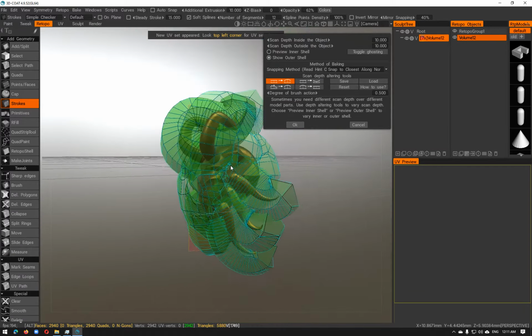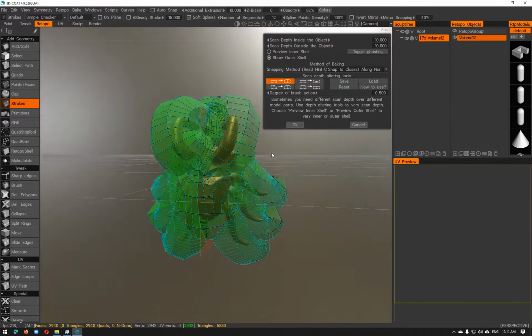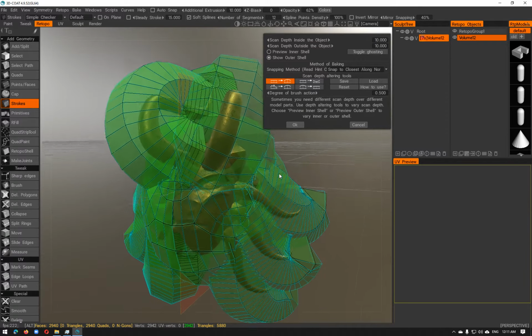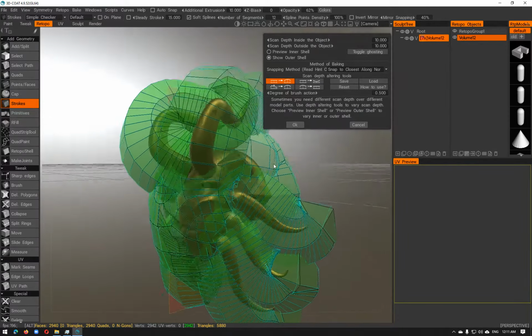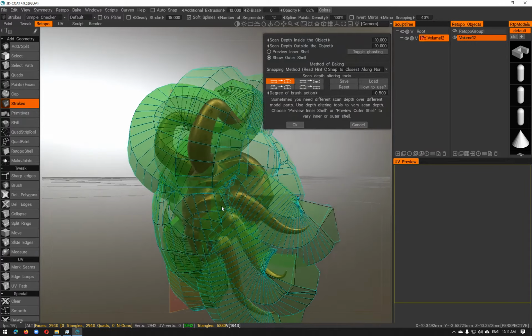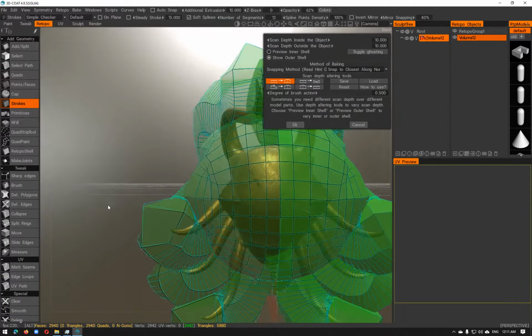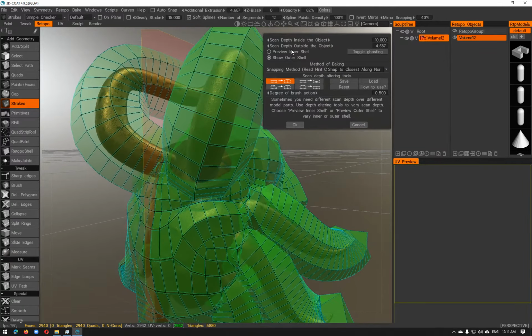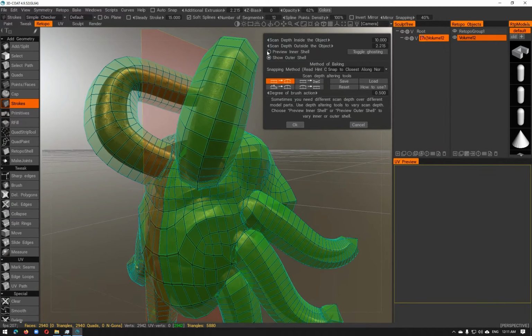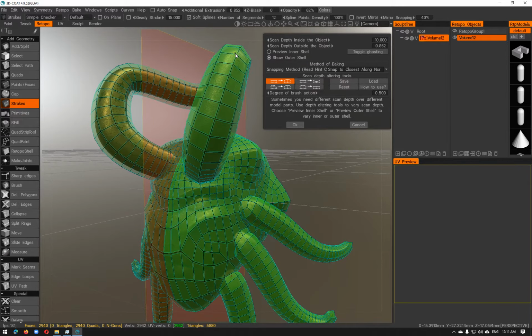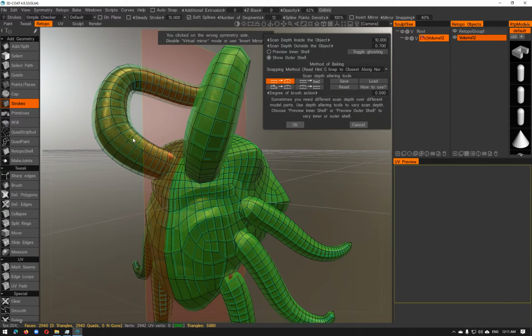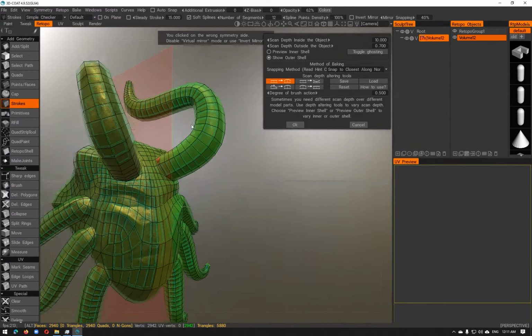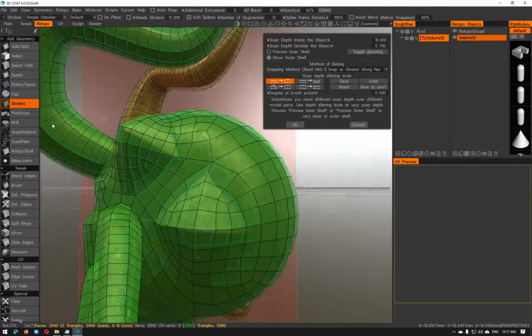So now I'm getting something that looks kind of strange, but since these details from my sculpting are going to be baked, it's going to bake a normal map from what I've sculpted, but also all the other properties of the shader. Just keep in mind that the bump will not be transferred from the texture, the bump will actually be transferred from the sculpting itself.